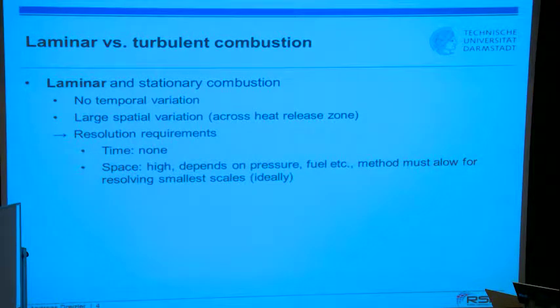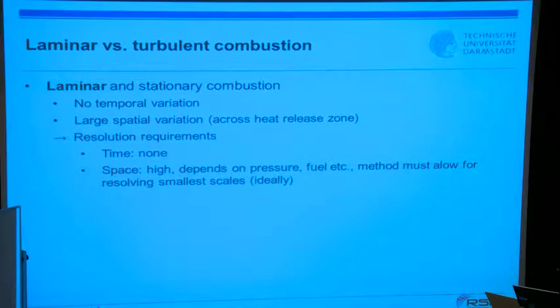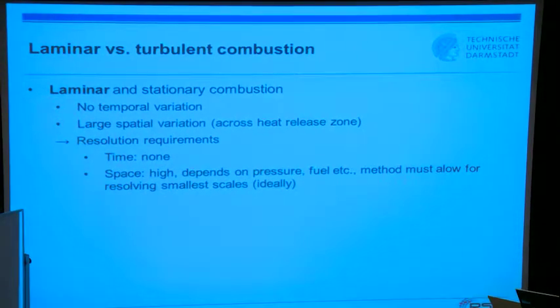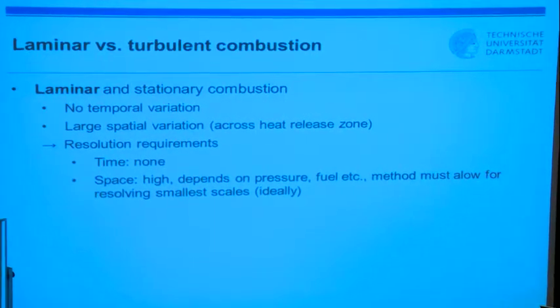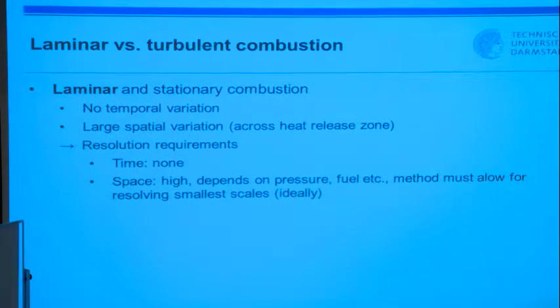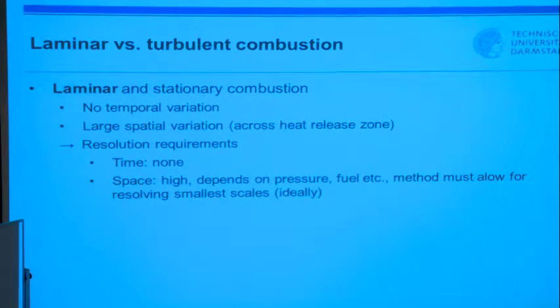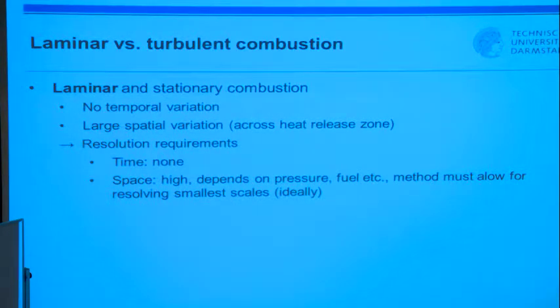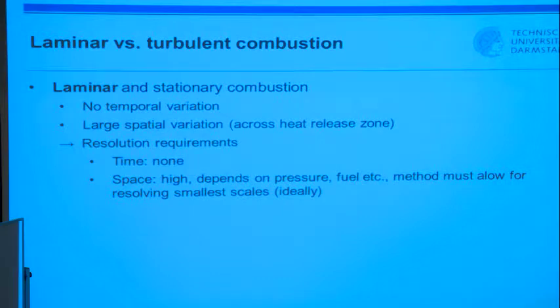Here we have to distinguish what we're after. If you want to measure the temperature in laminar flames under stationary conditions, then there is no temporal variation, but there might be large spatial variations, for example over the flame front. Of course, for increasing pressures this would get even steeper, and accordingly you would need to apply a higher spatial resolution. So the requirements in time are none, as long as you're stationary.